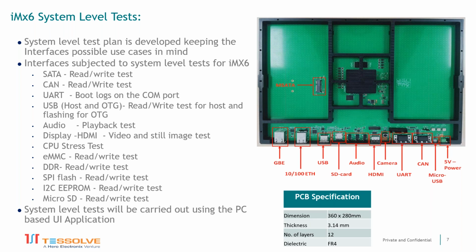Boot via the USB, audio display, CPU stress tests, eMMC reads and writes, DDR stress test, SPI, I2C, and the micro SD. So you're really using every interface and lots of different scenarios on that chip to put this through an SLT.